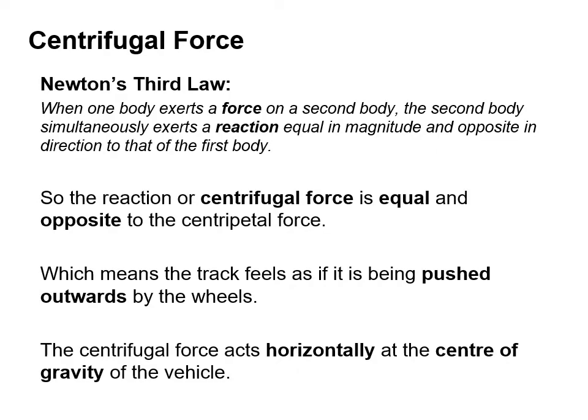So if we look at the centrifugal force now, we consider Newton's third law. So when a body exerts a force on a second body, the second body simultaneously exerts a reaction equal in magnitude and opposite in direction to that of the first body. So the reaction or centrifugal force is equal and opposite to the centripetal force, which means that the track feels as if it's being pushed outwards by the wheels. The centrifugal force acts horizontally at the centre of gravity of the vehicle.